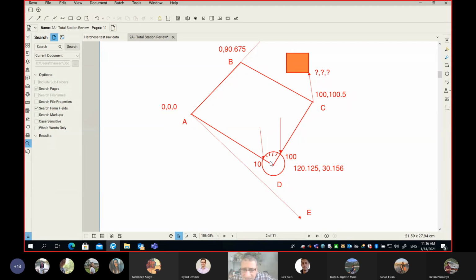Is it an angle, azimuth, anything? Is it a difficult question? It is an azimuth. So you're telling me that the 10 here, I'm saying I have done no effort. I just got my total station from the box. I level it, centered it above point D, and I shoot point A. I took the reading 10. You're saying that the 10 is azimuth, correct?